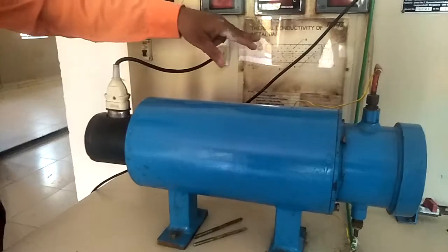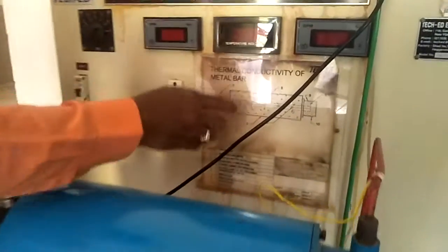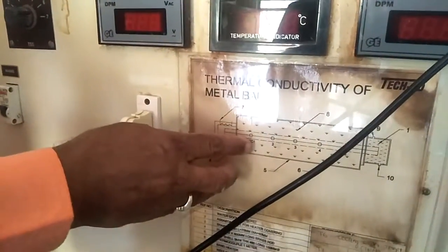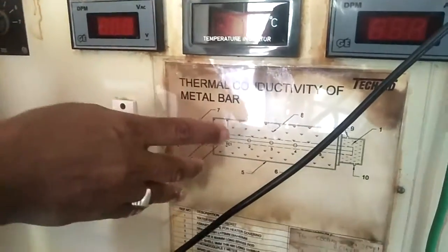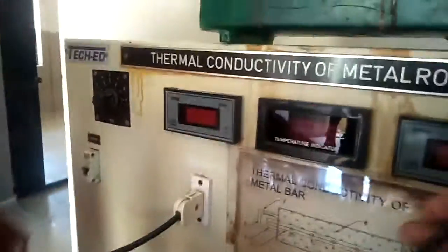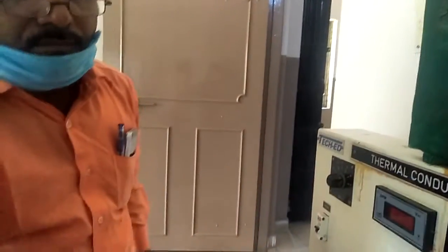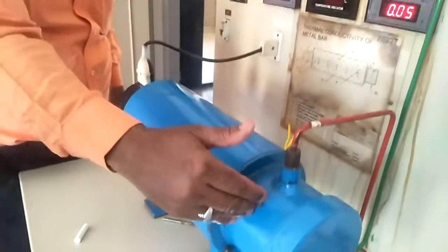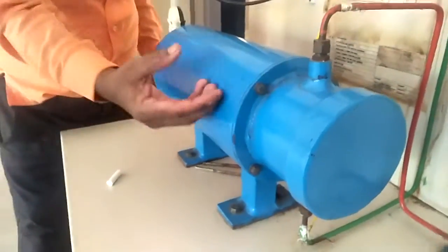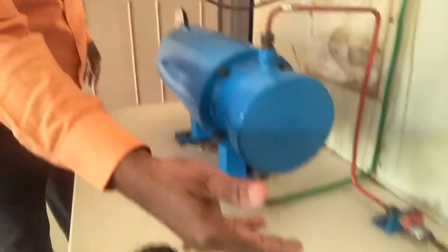The length is given. We will divide that length at different points like T1, T2, T3, T4, T5. So the total length whatever is given is inserted into the insulation, but one end of the rod is connected to the heater and another end of the metallic rod is inserted into the water jacket. Here the water from the tank will flow through this water jacket, and then by absorbing the heat from the metallic rod it flows out into the